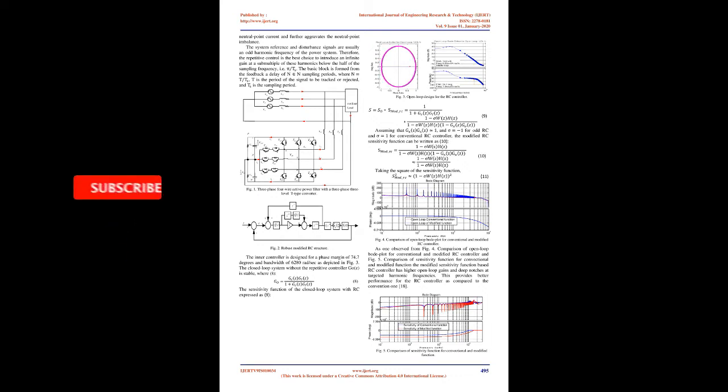The main objective of this controller is to achieve a unity power factor using the proper operation of two power switches and one AC power switch in each leg of the active power filter. The switching states in each leg to generate a unipolar voltage pattern are given as TX1 + TX2 + TX3 = 1, where Txi = 1 if switch Txi is switched on and Txi = 0 if switch Txi is switched off, and i = 1, 2, 3 stands for the upper, bottom, and inner legs respectively. Similarly, x = a, b, c stands for the three phases.